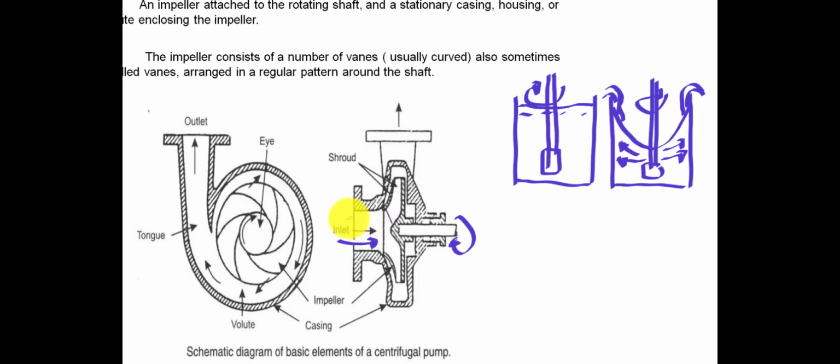So the same also is happening here. So nagkakaroon tayo ng suction of fluid at the inlet. So that is by means of rotation. Now the fluid is pushed on the side wall of the volute casing or ng casing ng pump. Now if you continue more revolution or angular velocity ng shafting, that produces a motion towards the outlet of the pump.